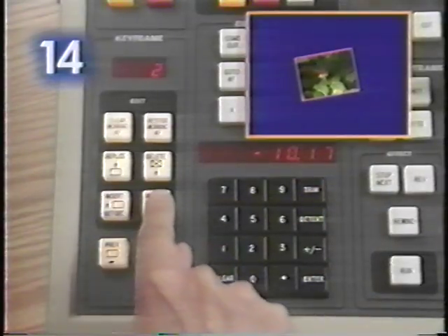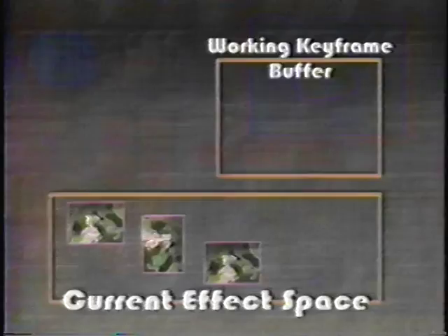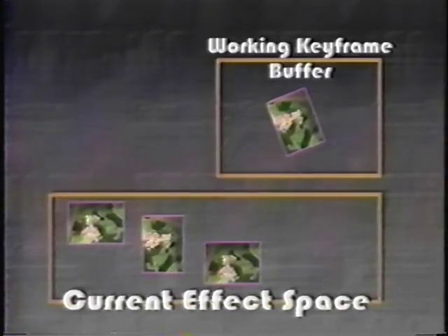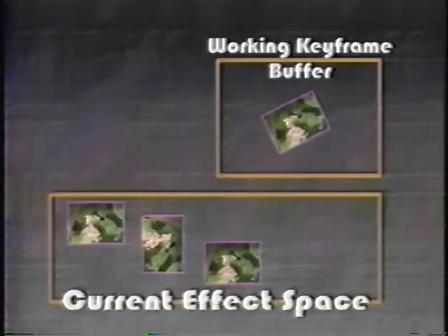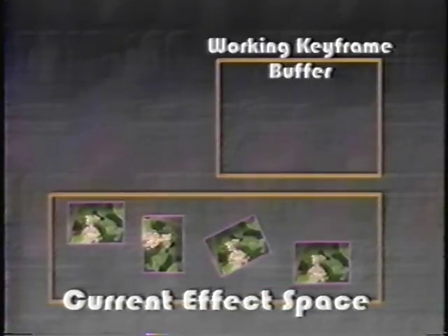To insert after, press Insert After, and the new keyframe will be inserted after the selected one. For example, if you selected keyframe number 2, the new keyframe will be inserted as keyframe number 3. All following keyframes will be numbered one digit higher than they were before.